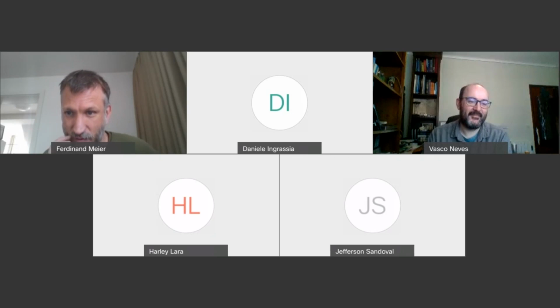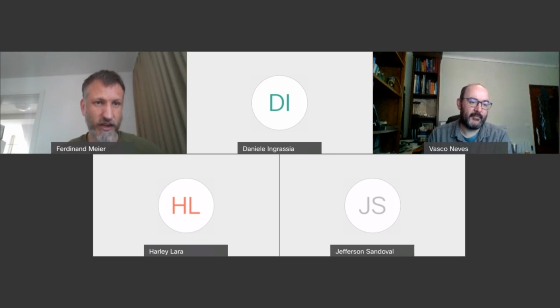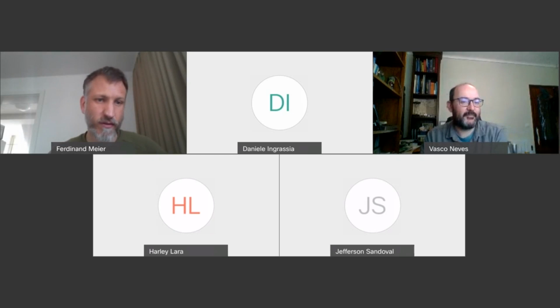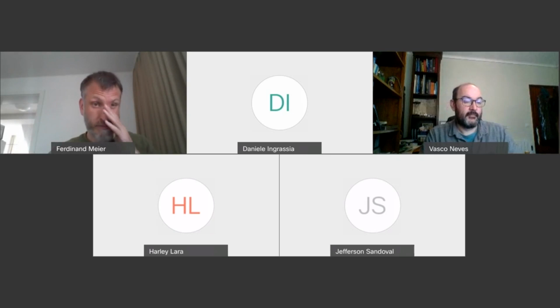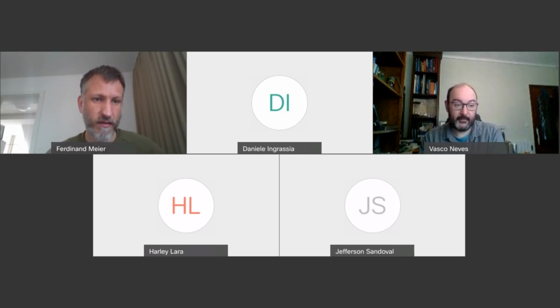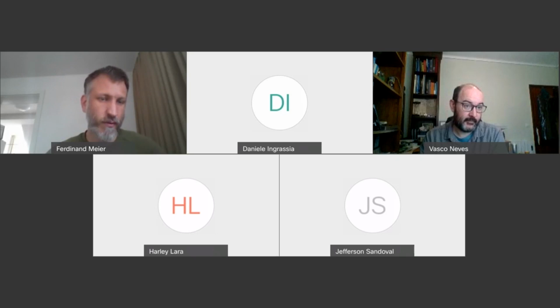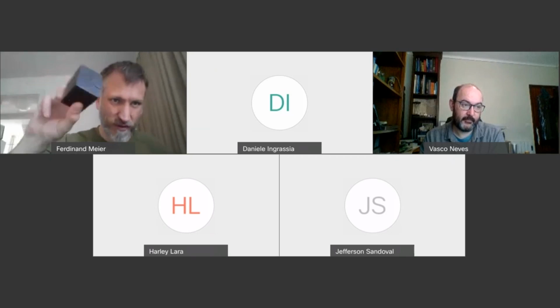Wait, I'm not going to do the practical part again. Oh, okay. Yeah, do the cut part, generate your G code. But you could perfectly do this on your small milling machine. You just have to be careful that you don't lose the 0 because you don't have end stops. And you should have the right milling bits. And I don't know how easy it is to get the materials in Aveiro. If you were in Lisbon, I could give you some advice. But yeah. Oh yeah, and one thing that I almost forgot, I will publish my recipe for this stuff here.